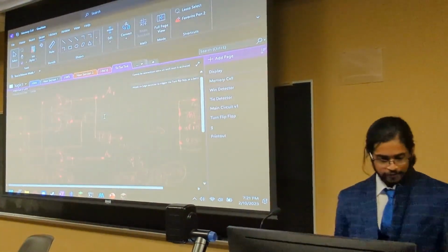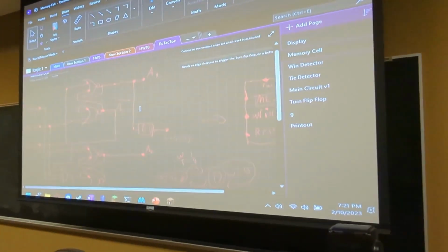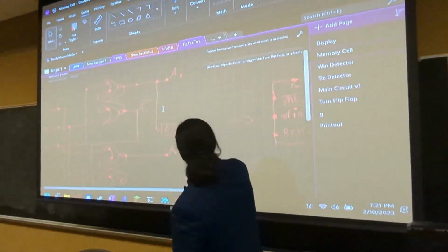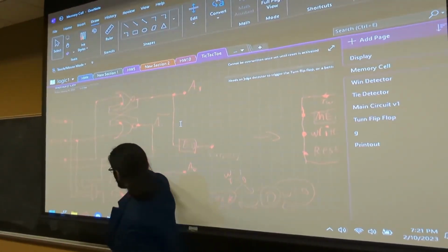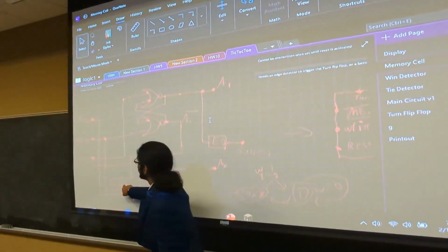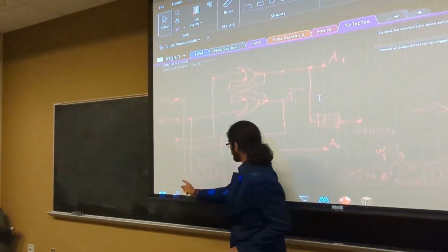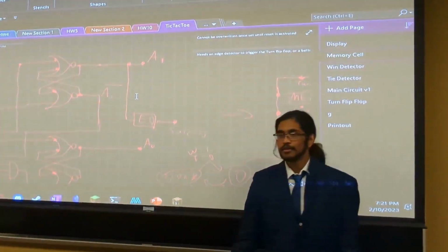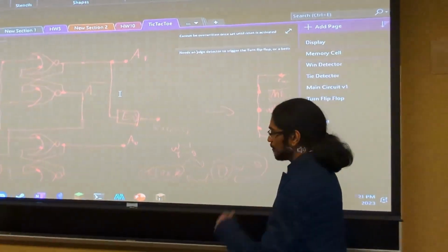So if A1, so this is the inverse of our outputted A1 signal, right? So if A0 is off, then that'll go into this AND gate. And if it is X's turn, then that'll go into the AND gate, and the right signal will go into the AND gate. And so all of those will set the bottom SR latch to 1, which will set a 1-1, right?